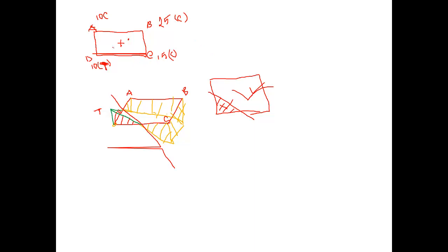Here you can see this is a footing, and this footing has 4 corners, and you have an eccentric load here, which is P. Due to this load, maybe at stress point A it is 10 compression, at B 25 compression, at C 15 compression, and at D 10 tension, sorry, not compression at D. Now we can draw the stress diagram, right?